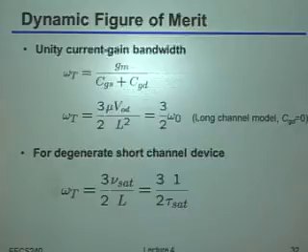I'm again assuming that all of you have seen omega t or ft many times before. As you should hopefully know, it's really set by gm over (CGS plus CGD). The real reason this is useful is that if you know what your omega t is, that gives you a really good hint as to how hard you are pushing on the transistors relative to the circuit bandwidth or characteristics you're interested in.